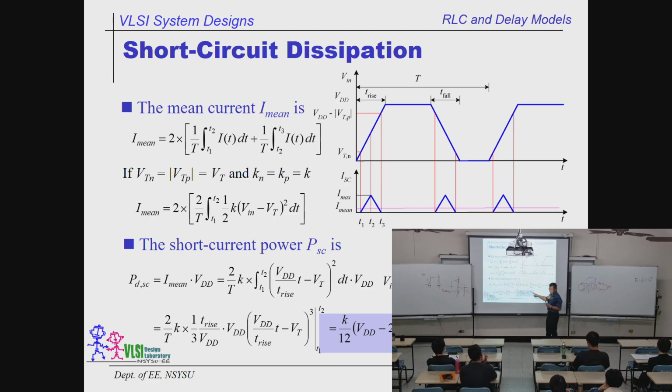It's a T rise. That is a rise time over the big T. Big T is a period. So how do we save the power? Pretty simple. Make these terms as small as possible, because we don't have a power to change the other factors. So this is the only power we have. We reduce the T rise time, and we can save a lot of the short circuits.